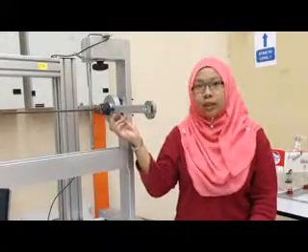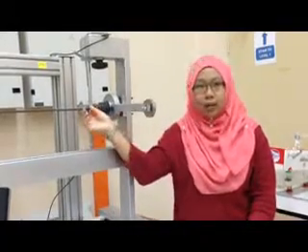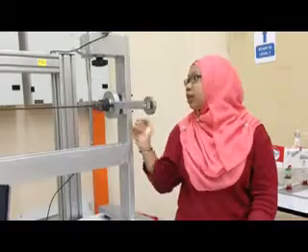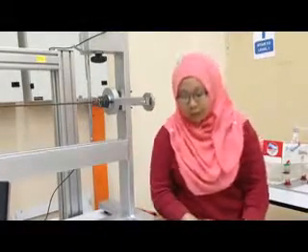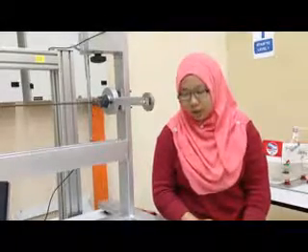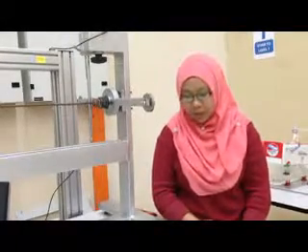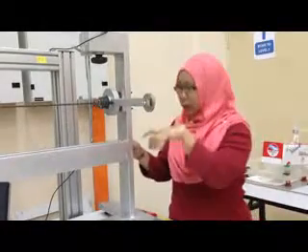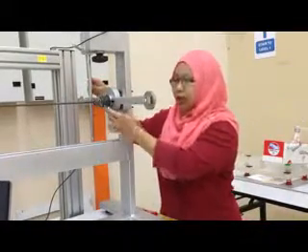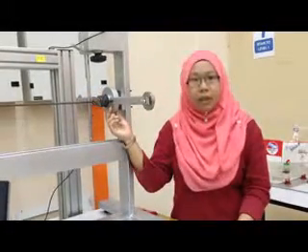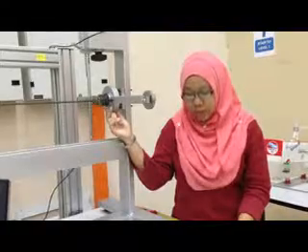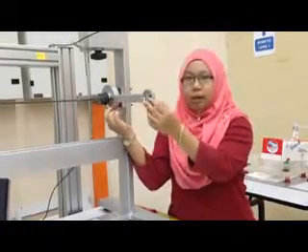Okay, for this experiment, there are a few components to take note of, which are the flywheel, the mass, the length of rod, and the LVDT sensor. There is also variable data which is important to take note of in this experiment. The first is the distance between the LVDT sensor and the center of flywheel. The second one is the mass and diameter of flywheel. And the third one is the distance between the mass and the center of flywheel.